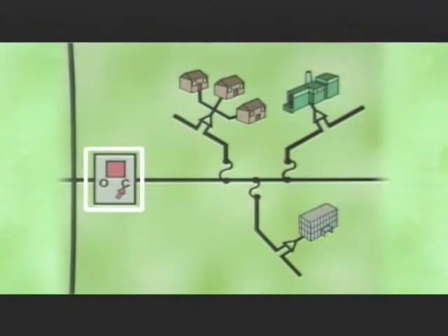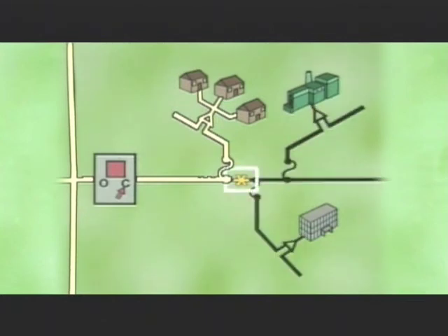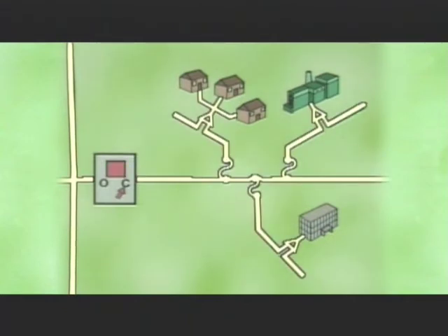At present, the circuit breaker and fuses are closed, and both the feeder and the laterals are energized. If a fault occurs on the feeder, the circuit breaker will sense the fault and open, momentarily de-energizing the feeder and the laterals. If the fault clears, service will be restored when the circuit breaker again closes. The fuses will not be affected in any way.